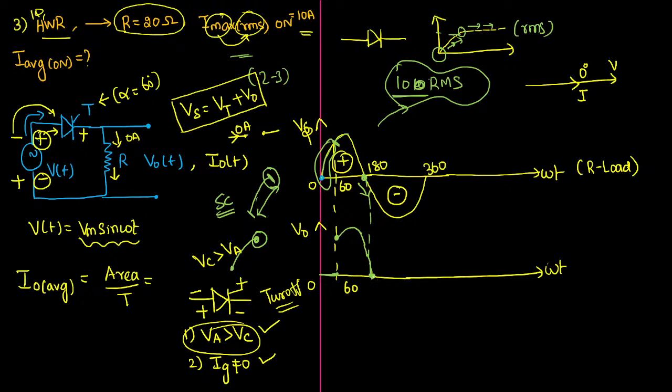If it is open circuited, then how will you draw the waveform? Again, the output voltage will become 0. Why? The moment the thyristor starts behaving as an open circuit, the supply voltage will be blocked, or dropped across the thyristor. It will not be allowed to the output side. So till 360 degree, there will be no output.